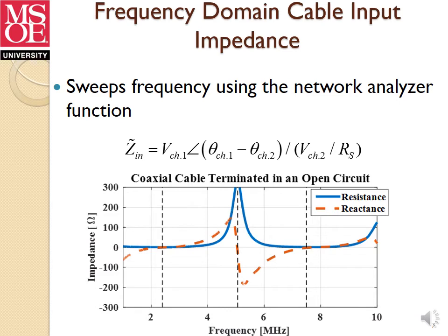Finally, using the network analyzer function to measure the channel voltages over a swept frequency range, the phasor input impedance of the open-circuited cable can be measured as shown below. This essentially turns the Analog Discovery Board into a portable, one-port impedance analyzer.